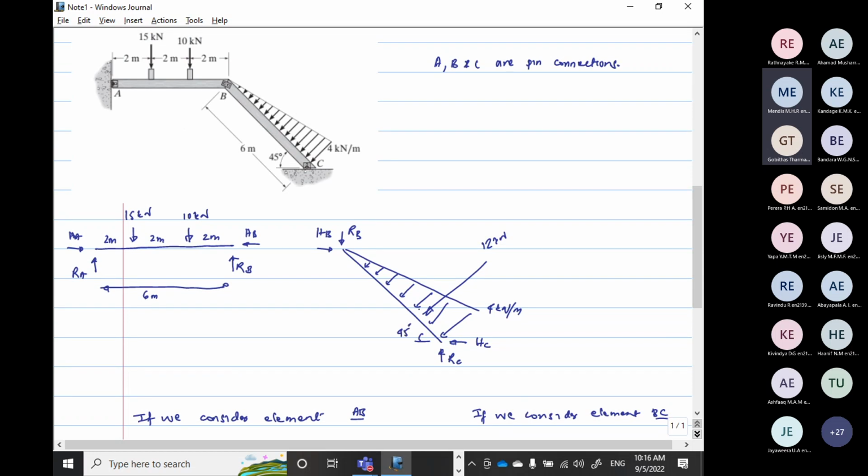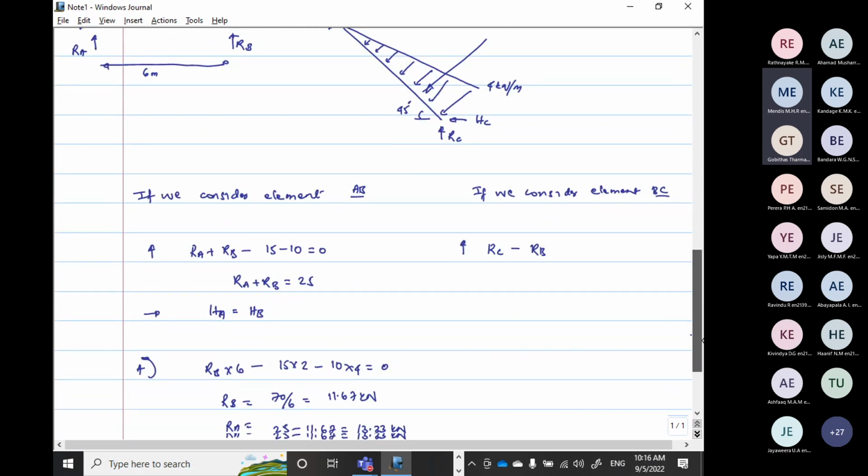Okay, so it is making 45 degrees to the horizontal reaction. So it has two components. You can break that 12 into two components, horizontal and vertical. That is the first thing we learned when we started structural analysis or engineering mechanics. The force can be divided into two components, or two components of the forces can be merged into one equal reaction. So the 12 will have two components, 12 cos 45 and 12 sin 45. The 12 sin 45 is vertical, 12 cos 45 is horizontal.